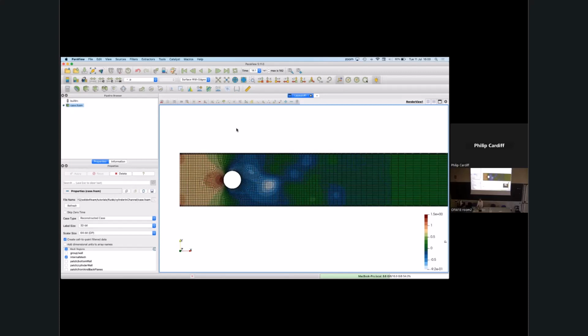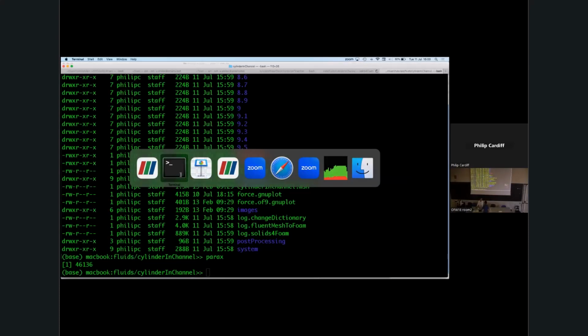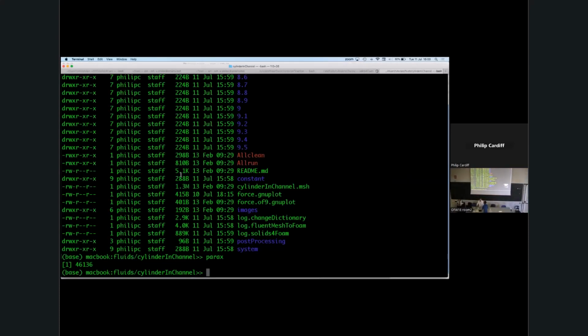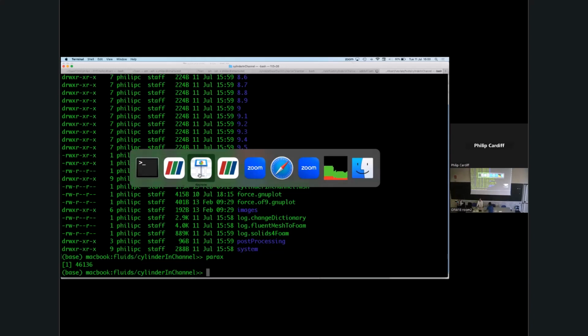It's curious as well, because if you run the three different versions supported, there are three different ports of pimpleFoam. Actually, the foam-extend 4.1 version of pimpleFoam is a little less stable for some reason. But you get slightly different answers with each of them.